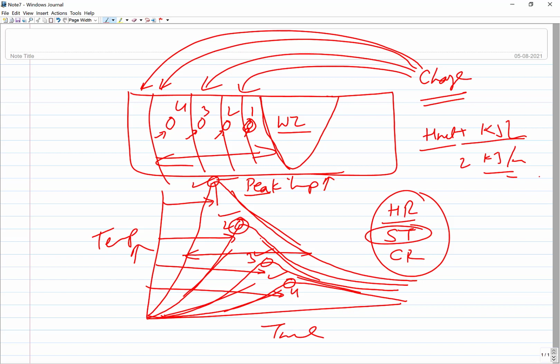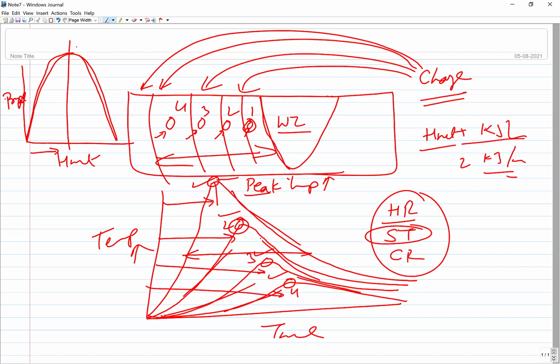So these are the weld zone and the heat affected zone related things, and how do we try to understand that? I will plot one simple diagram, probably I have used it earlier somewhere. The heat input and the performance or the properties of the joint goes like this. See, if you initially increase the heat input, properties will go high, then they will start deteriorating like this. So there is an optimum value.